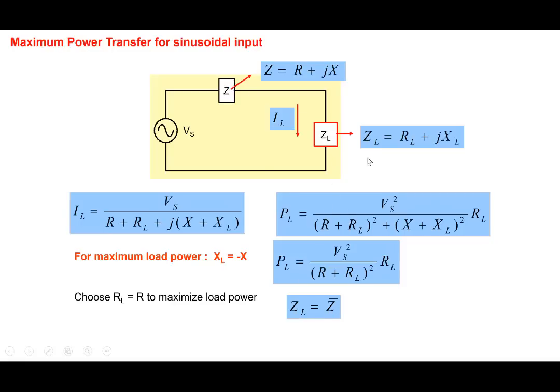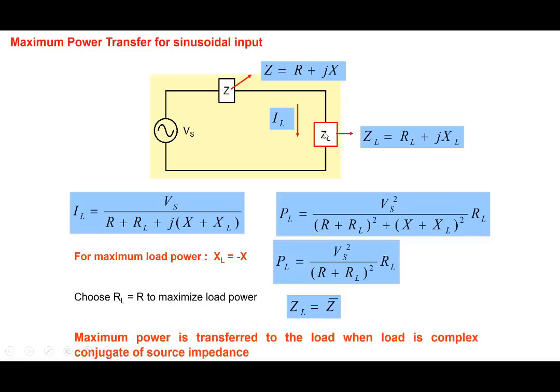So if you do that, then you will get maximum power transfer to the load here, right? So that's a generalized maximum power transfer result when we have the concept of phasor here. When we have inductors and capacitors in the circuit, then we have this general result: choose ZL to be the complex conjugate of the Thevenin's impedance here.